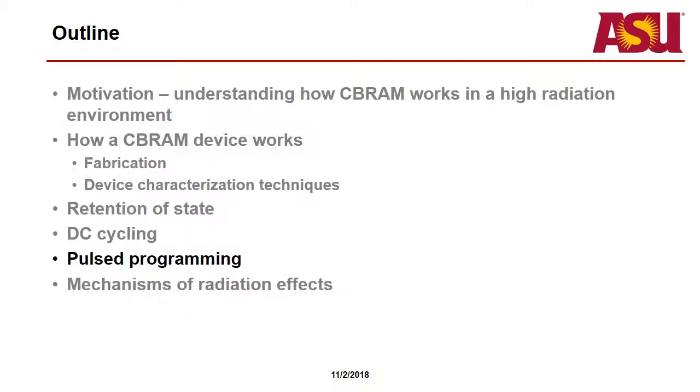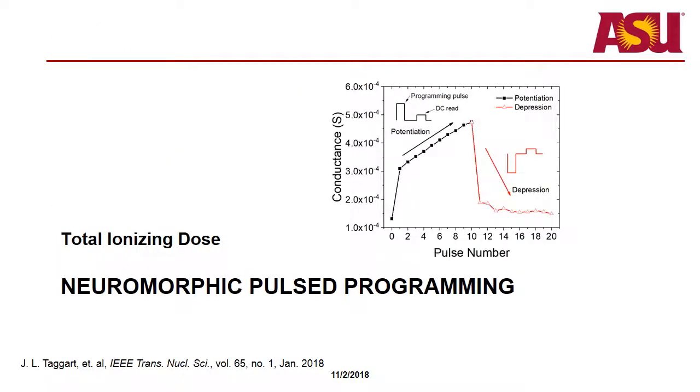Okay, so next I'm going to get into pulsed programming. In this case, prior studies have already looked at endurance tests. So for these tests, I'm going to talk about neuromorphic applications, using shorter pulses than you would for standard pulse cycling tests. Instead, we'll do incremental steps up in the conductance, or doing depression-related programming. So essentially, using the same pulse and then slowly erasing the device as well.